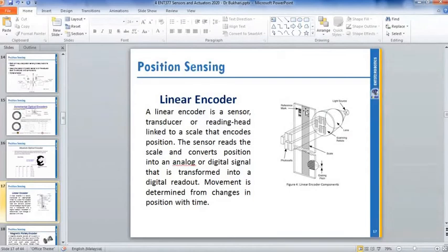Actually, your motor is following this strip encoder, the linear encoder, similar to an incremental encoder. What this system requires is only a limit switch to reset the position. That's why after you finish printing, your machine will go to the reset switch, to reset all the position readings.